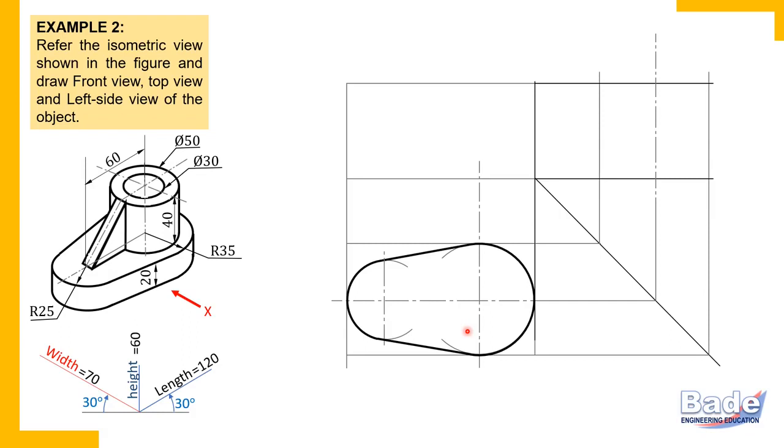Now, if the circular surface of the cylinder is parallel to HP, then in the top view it appears as a circle, and the remaining two views are rectangles. So many parts of a machine you will be able to complete using this simple logic. In a view shape, the remaining two views are rectangles.